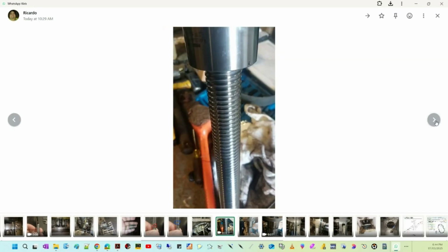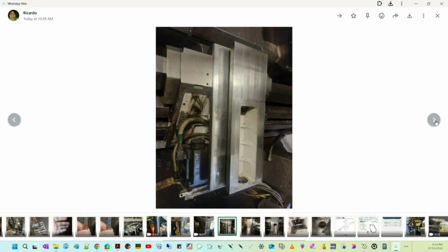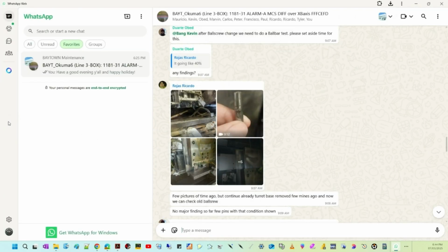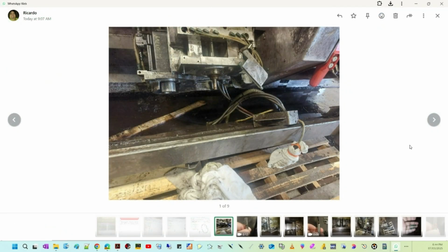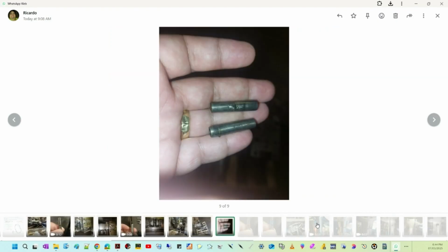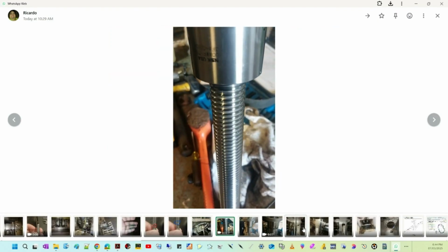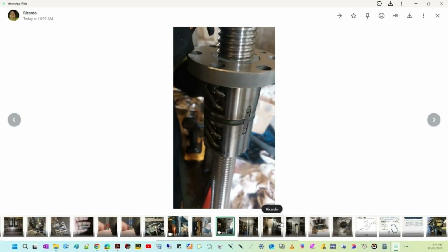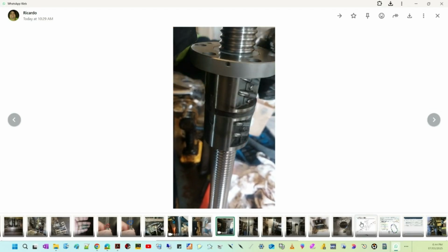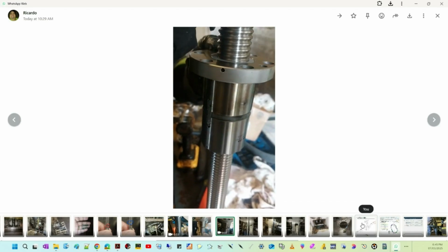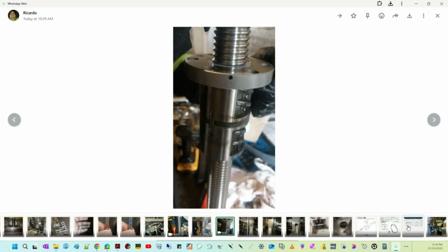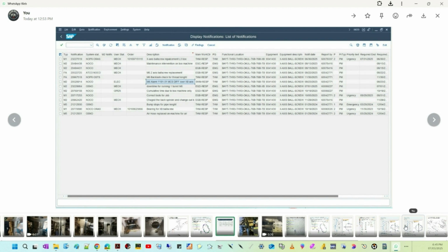And looking back at those work orders again, WO1009715115 was for this current ball screw change. But the previous one, 101-962-5866 from November 23, was only for bearings. And the same alarm happened back in August 23, too. Yeah, it suggests this might have been a developing problem, or maybe the previous bearing replacement didn't fully address an underlying issue, perhaps related to the ball screw or alignment, that led to this subsequent, more catastrophic failure. It definitely seems like a recurring weak spot for this Okuma.